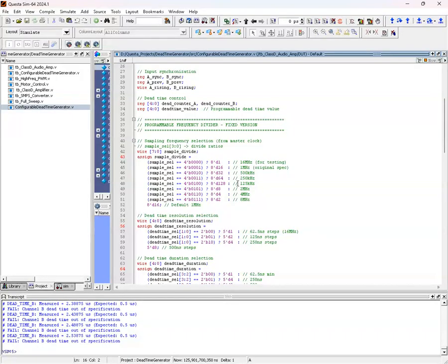If you have an SG3525 pulse width modulation IC for power supply, I believe those have some dead time control. You could determine that with a resistor, right? But it's not programmable. It's analog because you're using an error amplifier, with the inverted and the non-inverted inputs, and they can use a triangle wave from the timing capacitor, and the resistor they can use for current control to determine a voltage in the error amplifier. So let me just open some fact.